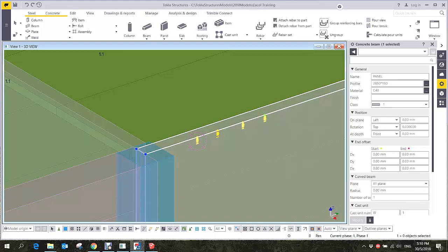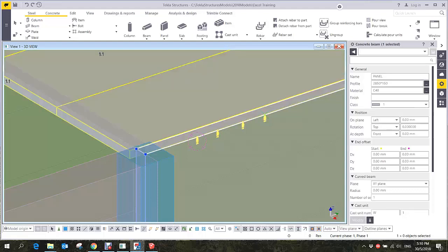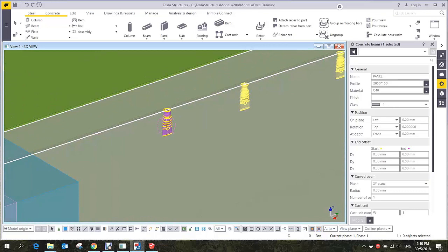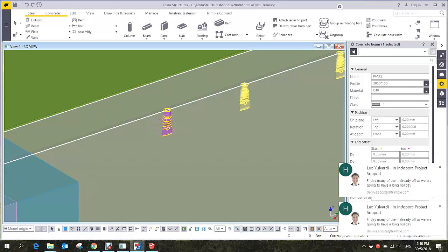You can choose to include, you can choose to exclude, because the practice right now is that this one is a pair. The production will come with this cost, so we don't really include it. If that is the case, you can exclude that one in the bar bending schedule. But if we want to show that one in the drawing, we can still model it. But I remember Mr. Paul wants to include that on the bar bending schedule.